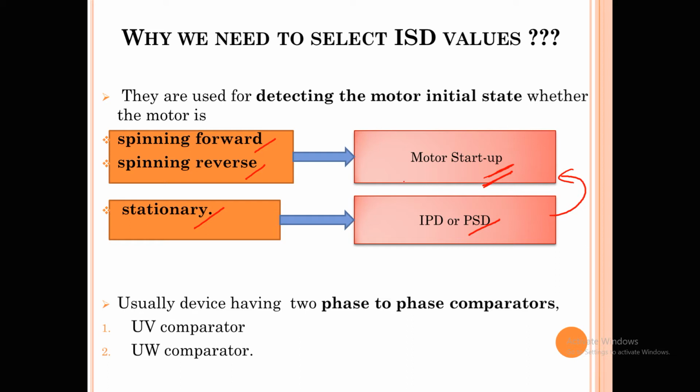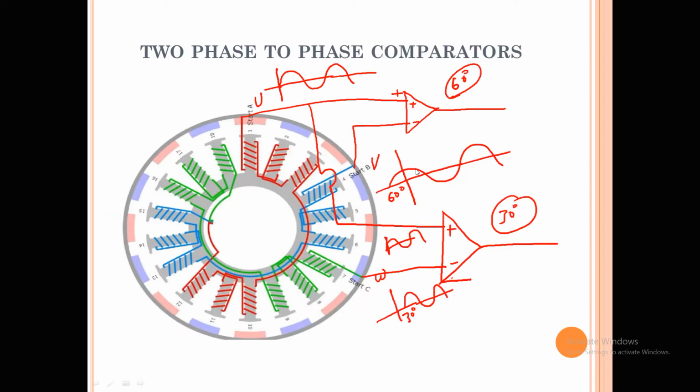A common doubt that comes to mind is what spinning actually means. Let's assume you turn on the motor and it is running at a certain RPM, like 350 RPM, and at the same time you switch off the motor. Assume a condition where the motor has not come to rest and is still rotating. If you switch on the power supply at that time, the device will first find these phase differences I have discussed.